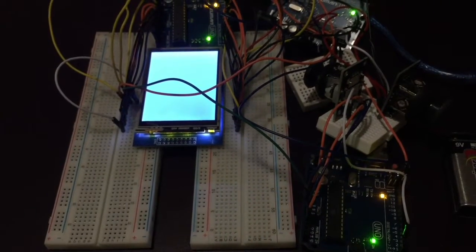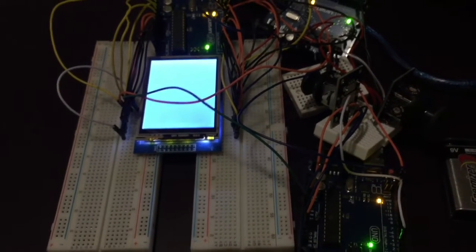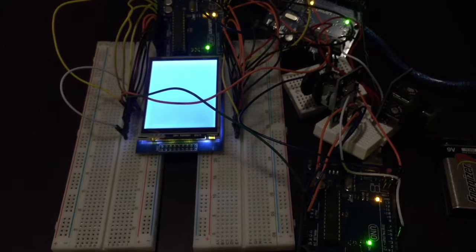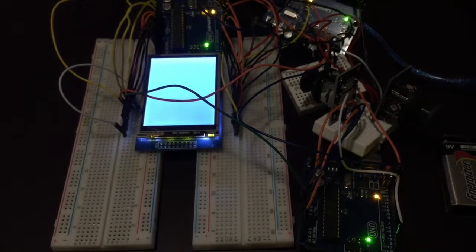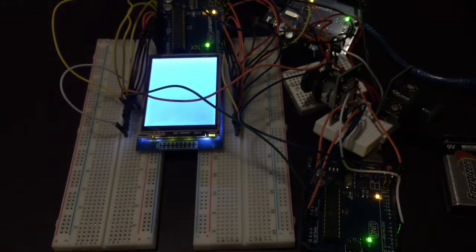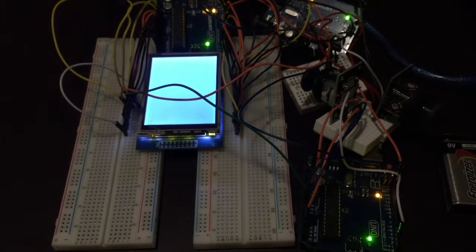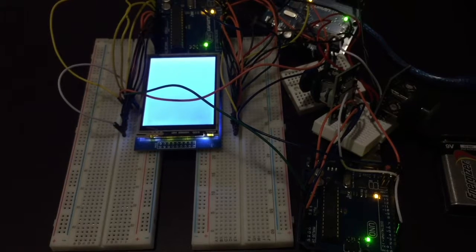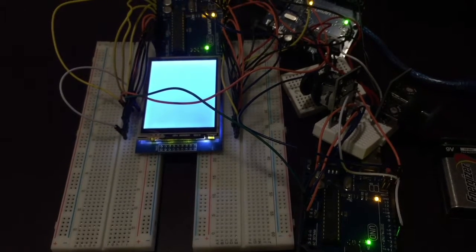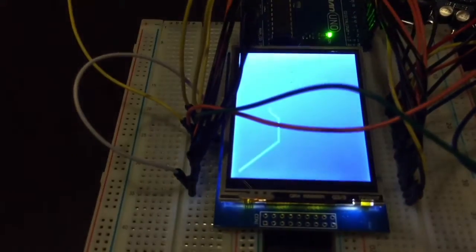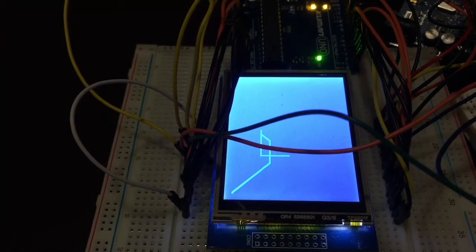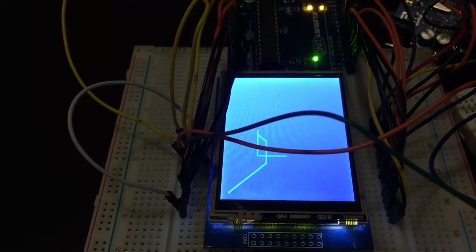How the slaves work, these two Arduinos, is that in their setup function, they set up a request handler from master, which uses the wire library, such that when master sends out a request using the same wire library, the slaves will call a specific function that is specified in setup. When this is called, they'll get the current reading from the analog sticks and convert that into an enum, which ranges from 0 to 9.